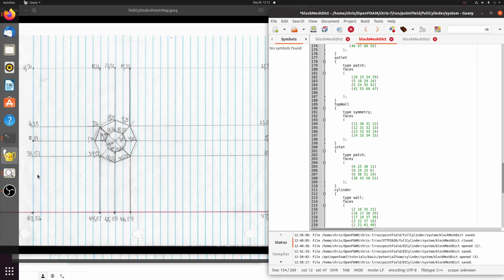A face is a little more difficult to see on two-dimensional paper, because you have to look from the inside of the block out, and then you go clockwise on the face that you run into. If you're walking from the inside out through a door frame, for example, that's the face. You look at the bottom left, top left, top right, and bottom right to get the clockwise direction. But we're looking at this from the front of the paper, so that's why I like the left and the right. The left is back, the right is front.